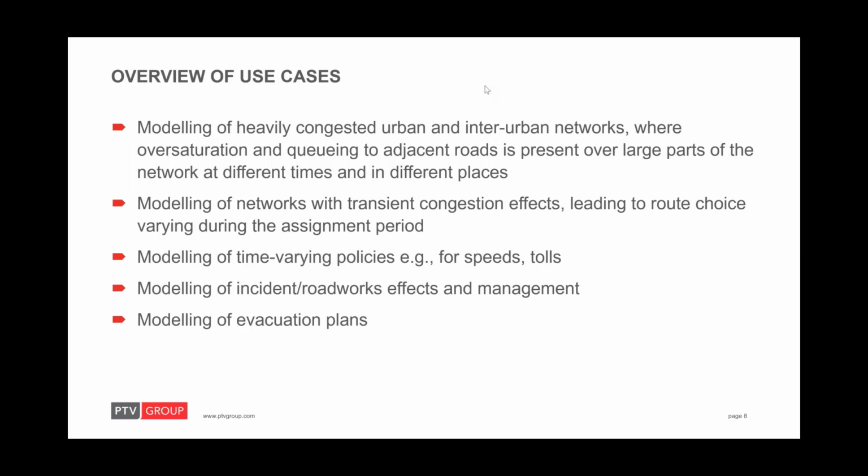And then if you have incidents and temporary closures that you want to model the impacts for, you can model such scenarios, and the overall network robustness or reliability and such, or management strategies for that can be evaluated by using simulation-based assignment. Finally, if you have evacuation plans, for example, hurricane evacuation and such modeling, that you would like to see the evacuation time in case of such adverse events, you can use simulation-based assignment as a support tool for estimating evacuation times in such emergency scenarios.